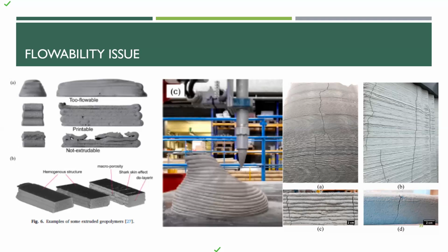So it also depends upon the actual printing requirement as well. If the mix hardens, like the initial setting time is like 1 hour, and you do it for a big construction, then when it goes along the perimeter of the rooms, it will take maybe 15 or 20 minutes, and then when the subsequent layer is placed, it will already be hardened as well. So this is an advantage of larger construction using 3D concrete printing.